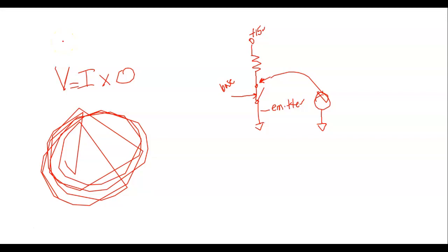So how much resistance does an open switch have? Okay, so that means all the voltage appears across an open. In a series circuit, you understand, all the voltage appears across an open. No voltage appears across what we call a short. It's not actually a real short. So if I saturate my transistor, how much voltage is it going to drop?